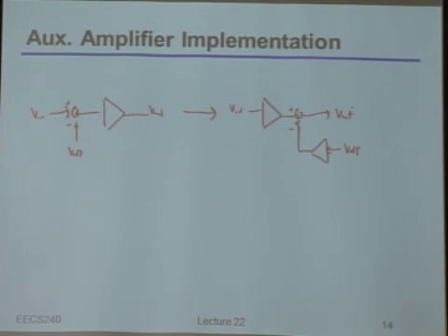There we go. If you use OTAs, you just sum the currents and then dump them onto the same node, and it'll get converted to a voltage. Okay, so let's actually just draw that block diagram quickly. So if this is my V in, I'll just draw this literally as a node now. This is my other OTA coming from a V offset. And then there's some fixed or common load resistance here. And then indeed, that's how I would implement something like this.